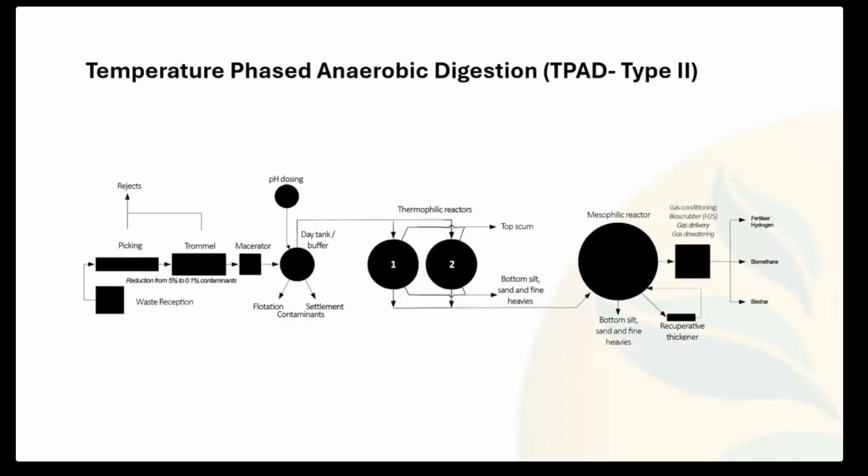This would probably even end up in South Africa if the project is accepted for implementation. We would have a mixed waste with a very low contaminant level that is further decontaminated from plastic and paper and timber residues. Glass and metal would be absent from the waste by default. Those rejects will be removed from the facility after handpicking, and a trommel screen removes other materials that would not be picked up by the handpicking.